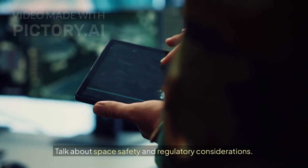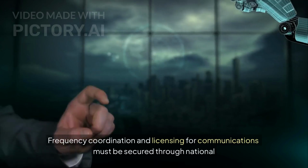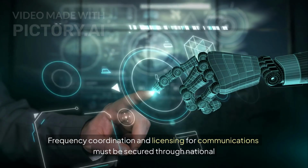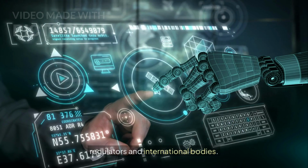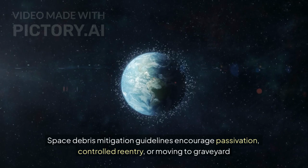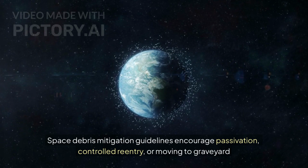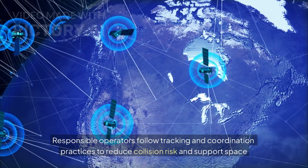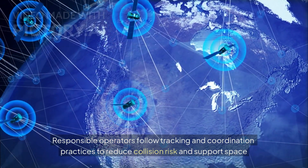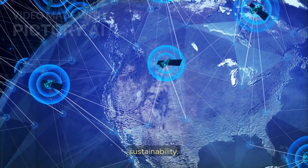Talk about space safety and regulatory considerations. Frequency coordination and licensing for communications must be secured through national regulators and international bodies. Space debris mitigation guidelines encourage passivation, controlled re-entry, or moving to graveyard orbits for GEO. Responsible operators follow tracking and coordination practices to reduce collision risk and support space sustainability.